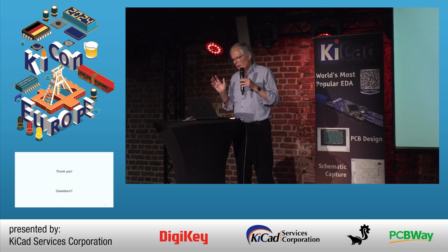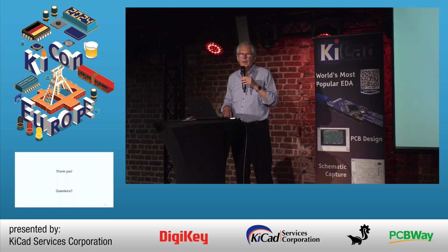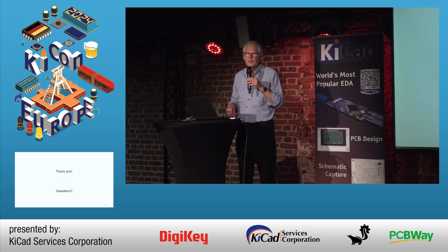Then you get a lumped element circuit out of your S parameters and can simulate that. What we cannot do right now is large signal S parameters or large signal RF. And this is what harmonic balance will offer. But this takes some time, ask me in 2 years.